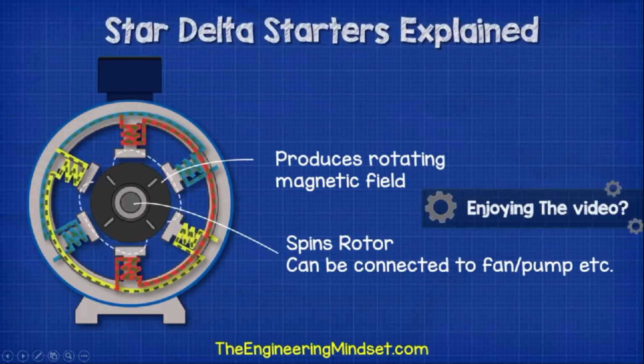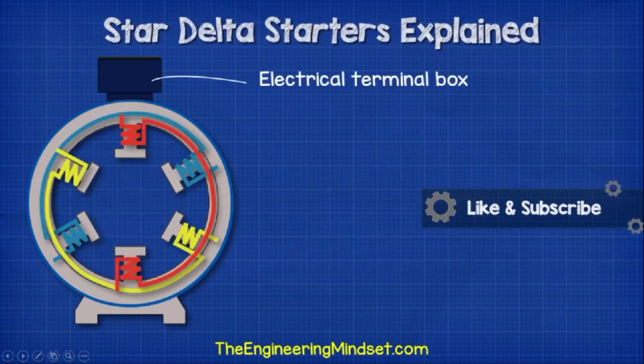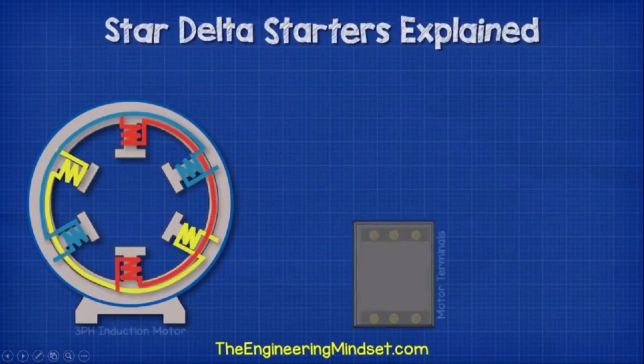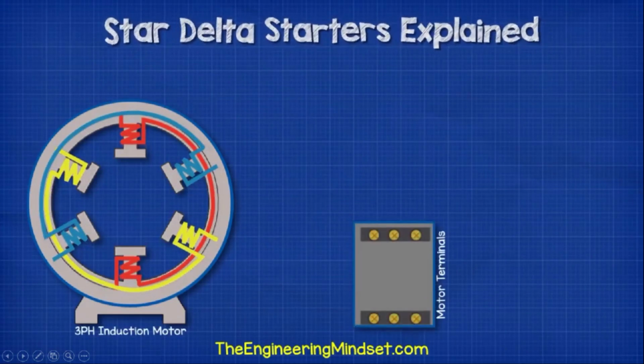On the top, or sometimes on the side of the motor, we have an electrical terminal box. I'll just move that box here to make it easier to see. Inside this electrical terminal box, we have 6 electrical terminals. Each terminal has a corresponding letter and number. We have U1, V1 and W1, and then W2, U2 and V2.